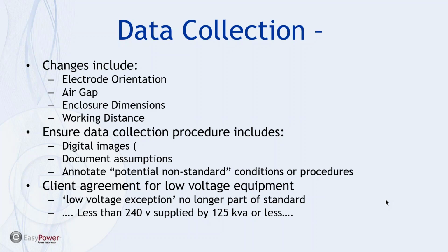Now all of these, and you'll see as we get into the device library, all of these have typical values as dictated in the standard by the IEEE. And so when we get into drawing the one line, by default, those standard values are available. And you'll see when we get into analyze or building the one line, it's not nearly as onerous as it could be. So basically the same recommendations apply, I think, with these new parameters as applied under the old standard.